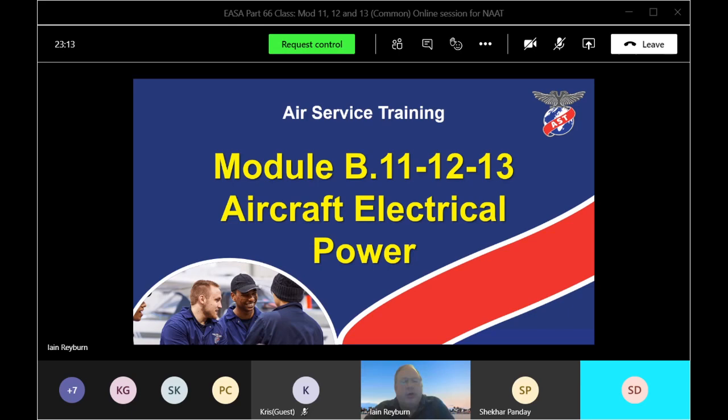is a TRU. Now, we talked about that in day one. A TRU is a transformer rectifier unit. Transformer rectifier. It takes the AC supply and converts it into DC. Now, it's a transformer, so the transformer changes the AC from a high value to a lower value due to the ratios between the primary and the secondary coils, the number of turns. So as I said on Friday, whatever comes in to a TRU, it'll be the same proportion ratio comes out because the ratio of the currents doesn't change.